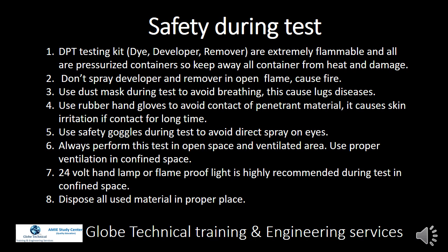Use safety goggles during the test to avoid direct spray on eyes. Always perform this test in an open space and ventilated area. Use proper ventilation in a confined space. A 24-volt hand lamp or flame-proof light is highly recommended during the test in a confined space. Dispose of all used material in a proper place.